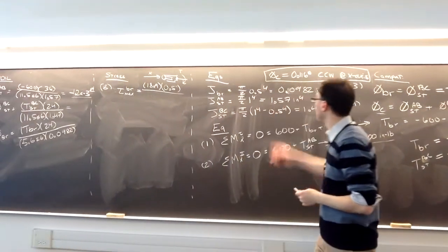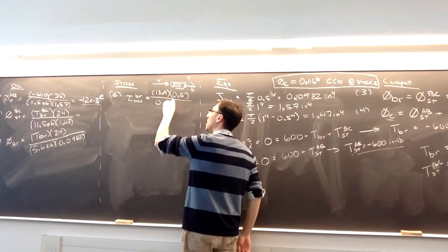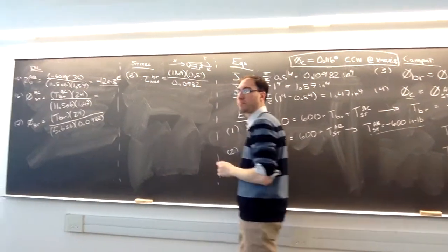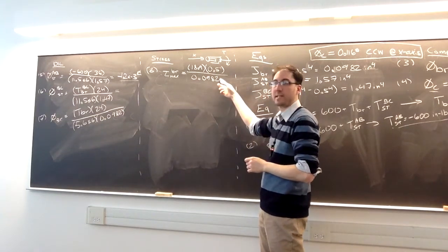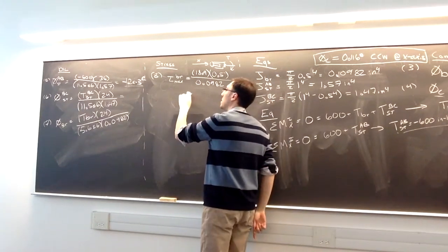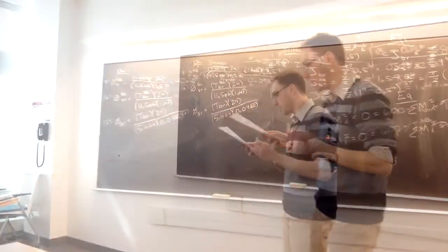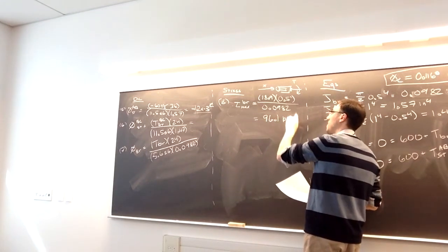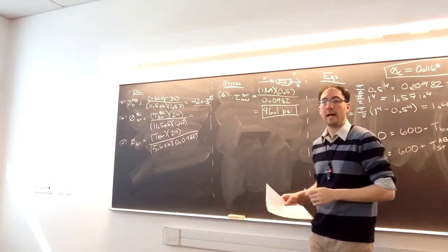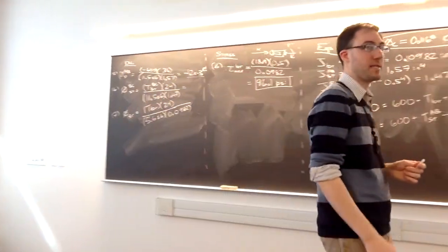And the J of the brass was 0.0982. This is in inch pounds. This is in inches. This is in inches to the 4th power. So the maximum shear we have in the brass will be in PSI. It should be at 96 or 96.1 PSI. And since that's the only section of brass we have, it must be the maximum stress in the brass.